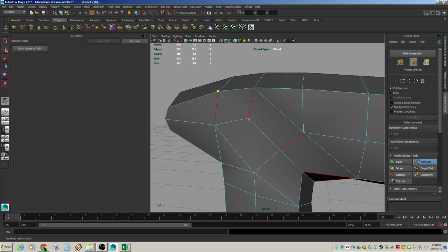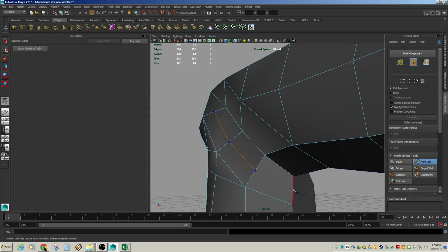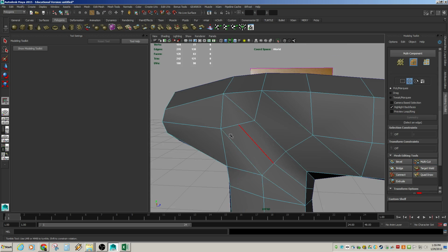So what I'm going to do is I'm just going to slice that into two triangles. Now the reason for that is because a triangle can become a quad very easy, right? It just needs one more point in it, right? And now that can be a quad. But now this is a five-sided face, and so we can just use this to insert this edge all the way down through there. Okay, so now this is a quad, right? We do the same thing on the other side.